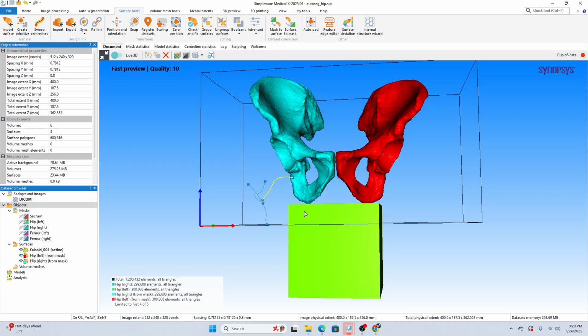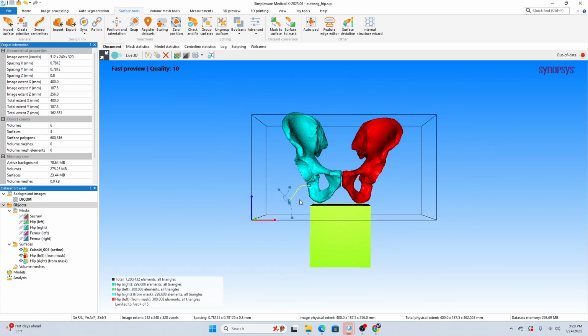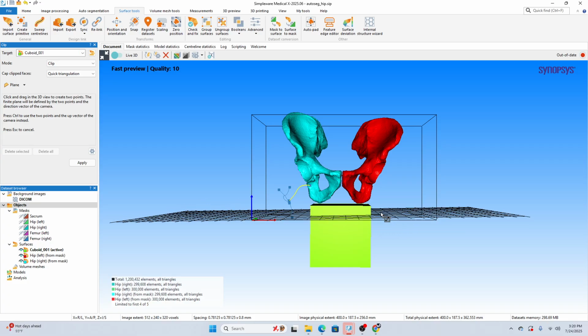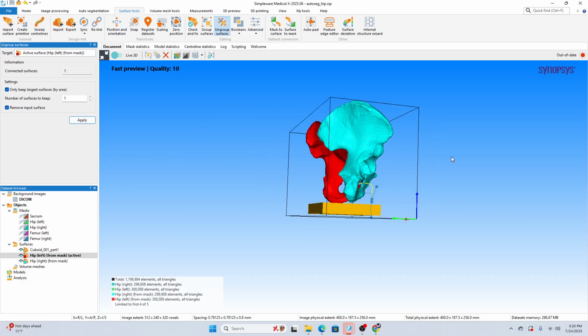So before that, I'll select a plane corresponding to which I need to cut out the surface. This is a proper plane corresponding to which I can cut the surface. Going into the advanced option, I skip out the particular surface, selecting the plane. Once this particular plane is selected, partitioning that out, this part can be easily removed. Now we have the desired part, we have the desired operation.